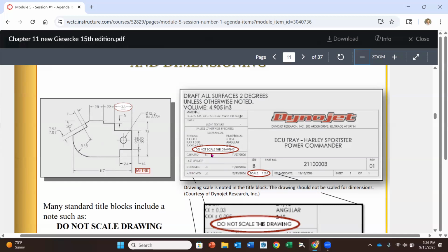We will always draw in a one-to-one scale. We'll pull our border in to fit around, which may require us to adjust the scale, okay? But we never scale a drawing that's been printed on a printer, because again, it's printed to size. So I don't want to take a ruler and measure something on it and then assume the dimension. No. You've got to have everything dimensioned so nobody ever has to do that. So you have to try not to forget dimensions.